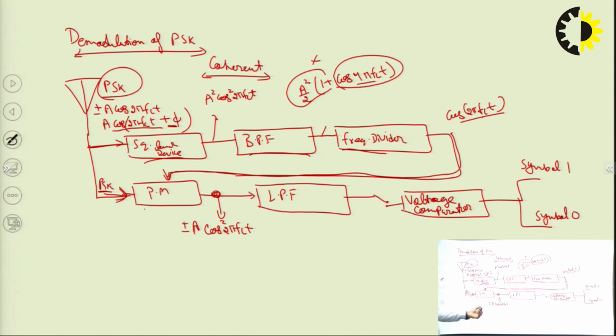So you can see we are generating the same carrier from this PSK waveform. That is very important to maintain the phase difference. We have to use synchronized phase, synchronized amplitude and frequency so that they match perfectly.